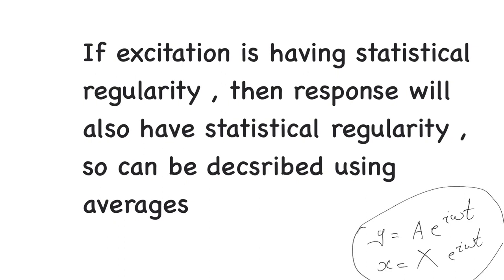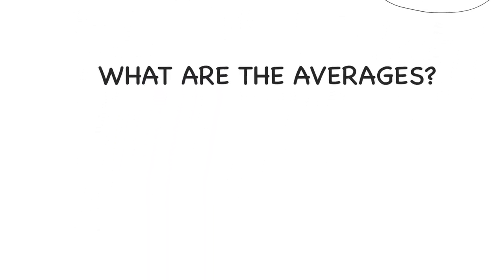Extending that concept into random vibration, we will end up here: if excitation has statistical regularity, then response will also have statistical regularity. So it can also be described using averages. So no more time description here. We will be describing both excitation and response in terms of averages.